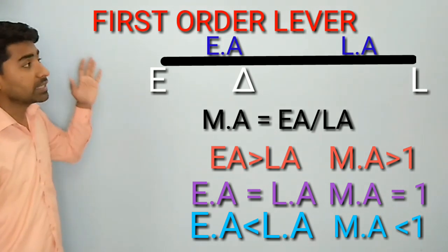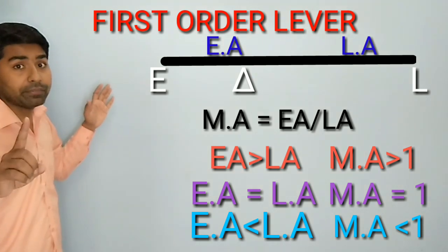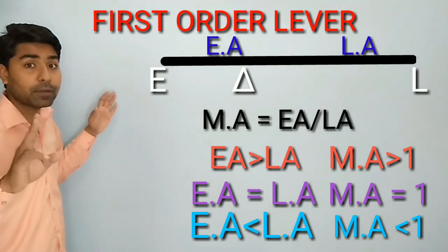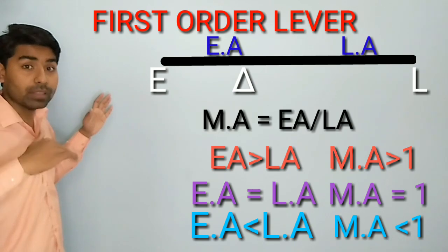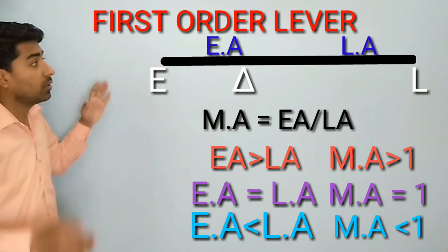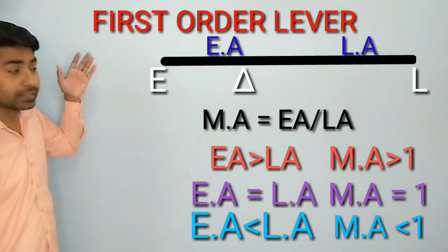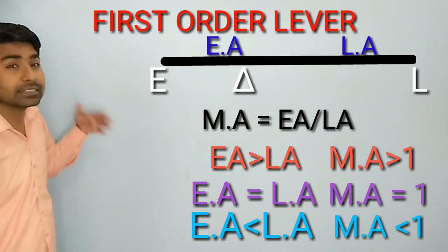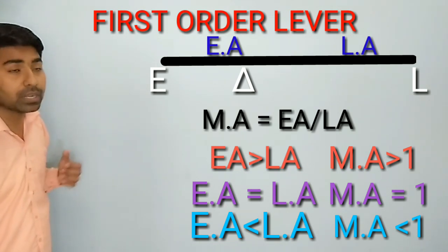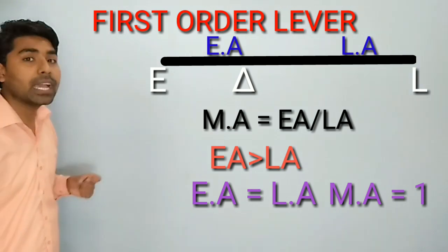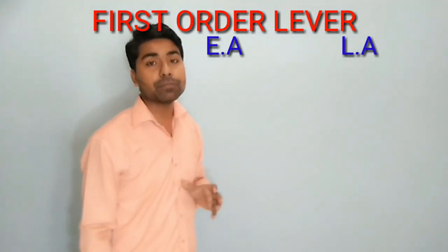So here a single lever, meaning the class 1 lever, can perform all the 3 types of functions. Class 1 lever only can perform all the types of functions. What? As a force multiplier, as a change of direction, or as a speed multiplier. Because the fulcrum can change position, the mechanical advantage changes and the function of the machine changes. This was about the class 1 lever.